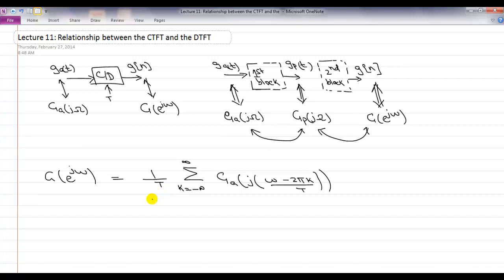Okay. So in particular, what we saw was that the π frequency in discrete time actually corresponds to the π by T frequency in continuous time. Okay. So that's sort of where the folding happens, right? π by T is the location where folding of your frequencies happen, and the highest frequency in discrete time is always π, which in relation to continuous time is π by T.